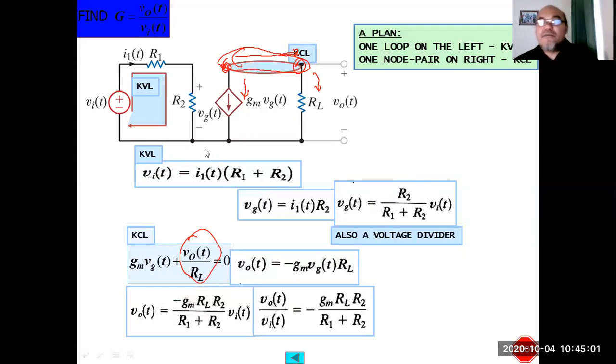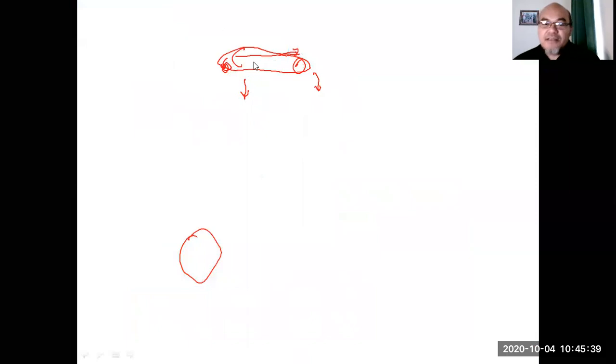One question from your friend is why we do not calculate the two sides together immediately, because they are connected here. In a transconductance amplifier they are connected, but usually we just calculate them separately, because the relationship between the left side and the right side has been expressed in the value of the current source: the current here equals gm multiplied by VGT. So there is no need to calculate again using Kirchhoff current law, for example, on the lower node here. That would just make things more complicated.